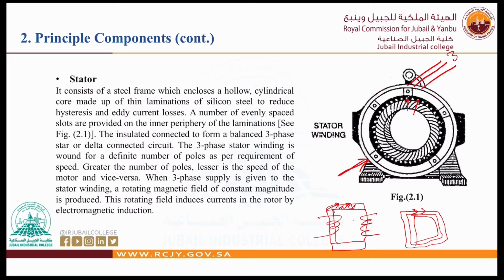If you apply three-phase voltage here, we will have, of course, inside three windings separated by 120 degrees, and the ends of the windings are either connected as a star, which is mostly used, or delta.